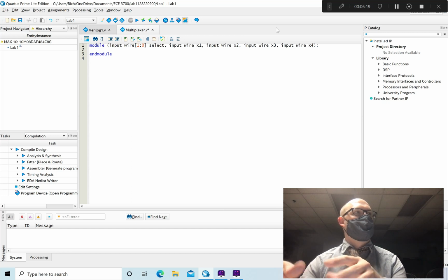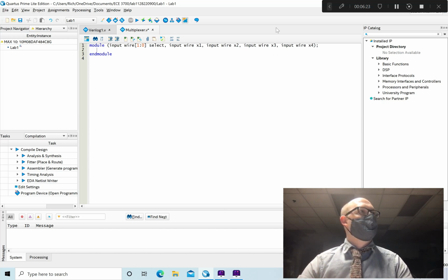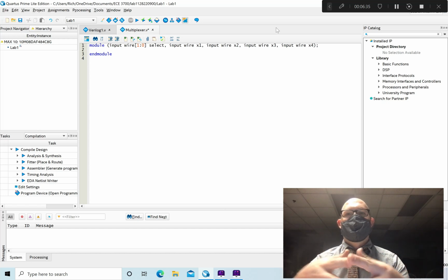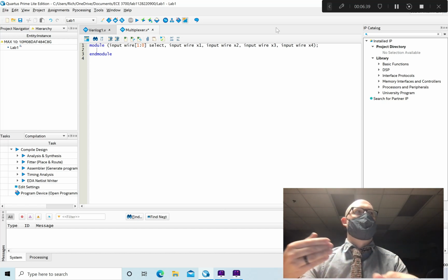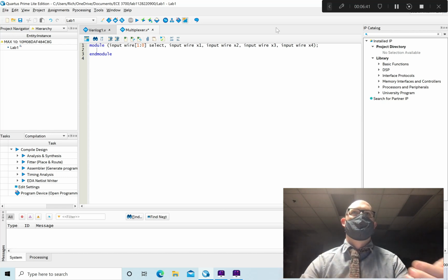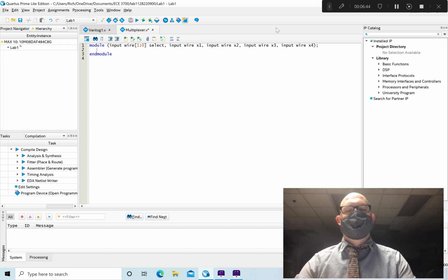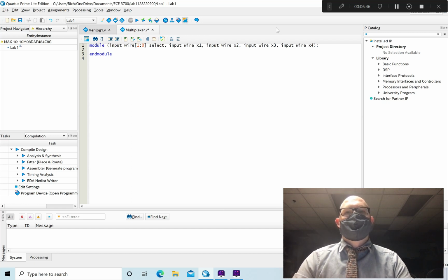Before I solder everything together, is this going to work? Yeah. An assignment level modeling, where you would do some optimization. So in structural modeling, or assignment modeling, we would say, I want this logic equation, and I want F to equal this. And then the compiler would go through and pick the most optimized gates to make that happen. So it's two different approaches; depending on what you want to do, you use one or the other, is what I'm trying to say.